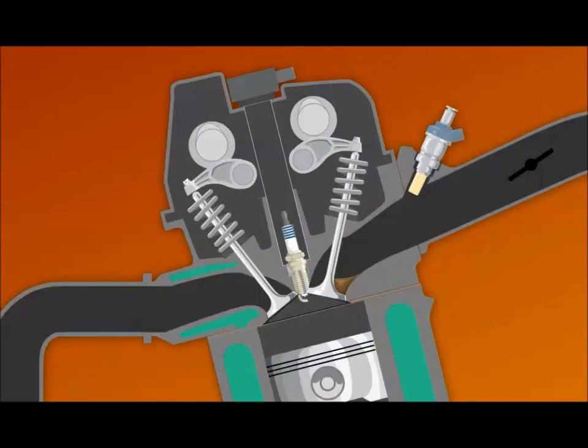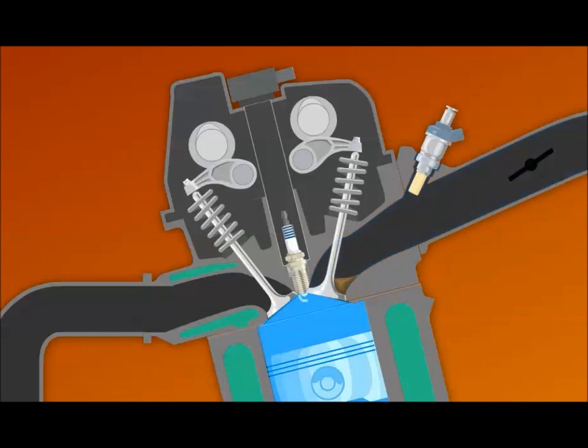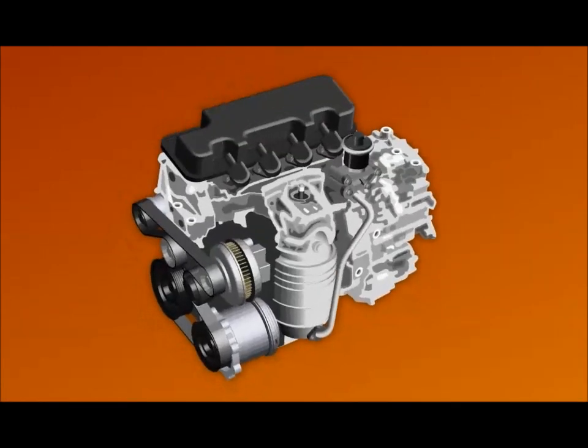Most engine faults affecting drivability involve problems in the intake manifold or combustion chamber. Faults such as intake manifold leaks, tight or leaking valves, or leaky piston rings can change the air-fuel ratio. These faults may lead to low power complaints or a rough idle.